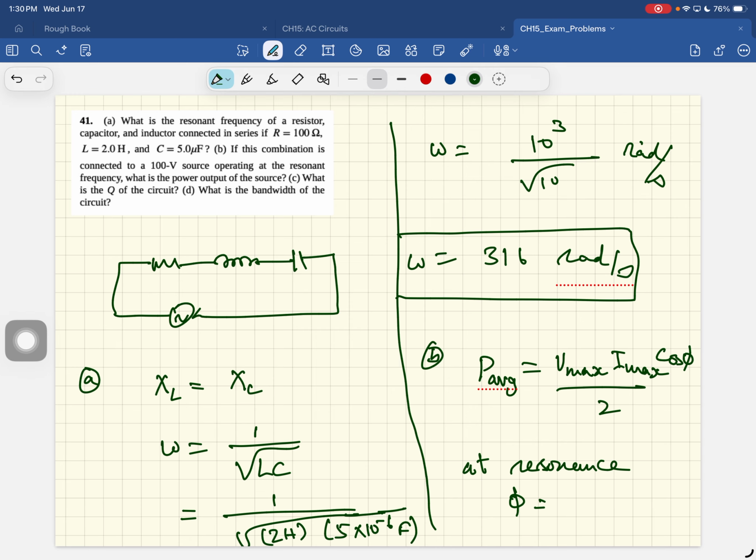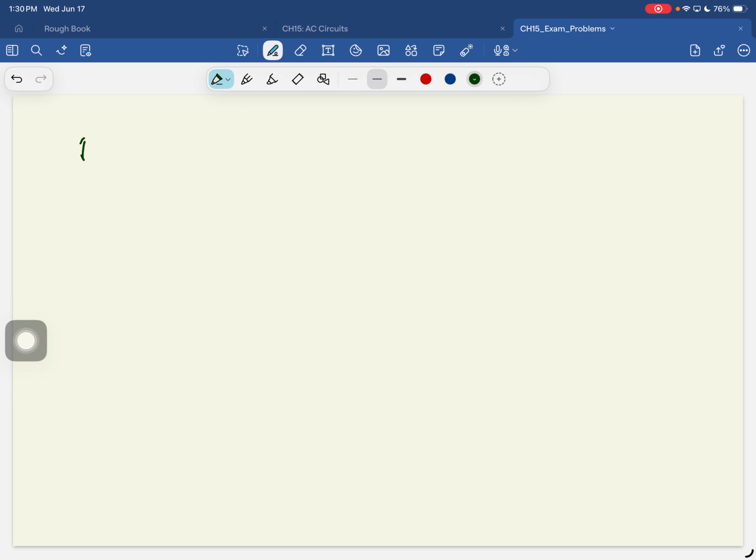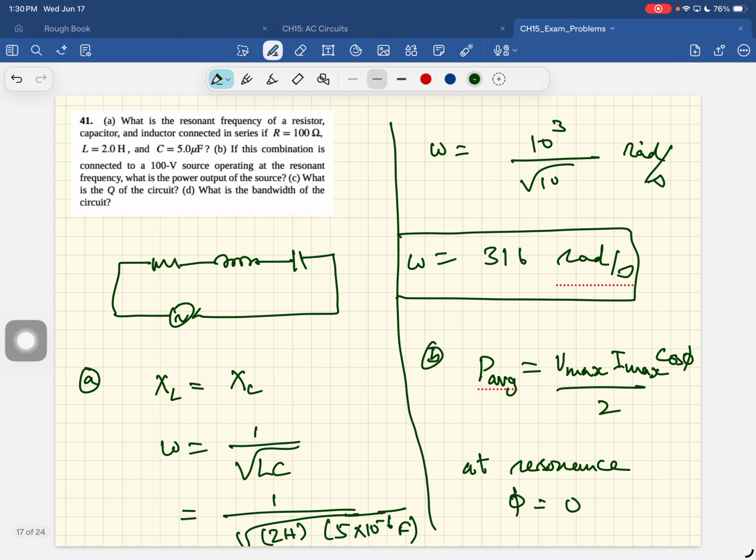And you would learn all of that as an electrical engineer. So a step-up transformer is designed so that the output of its secondary winding is 2000 volts RMS, when the primary winding is 110 volts line voltage. If there are 100 turns in the primary winding, how many turns are there in the secondary winding?